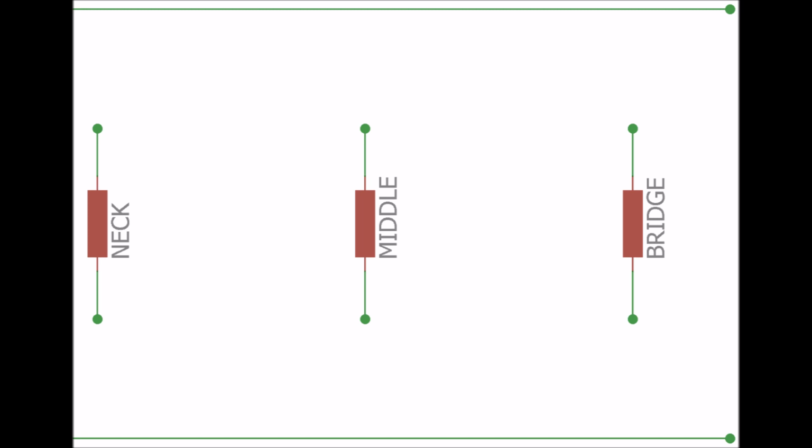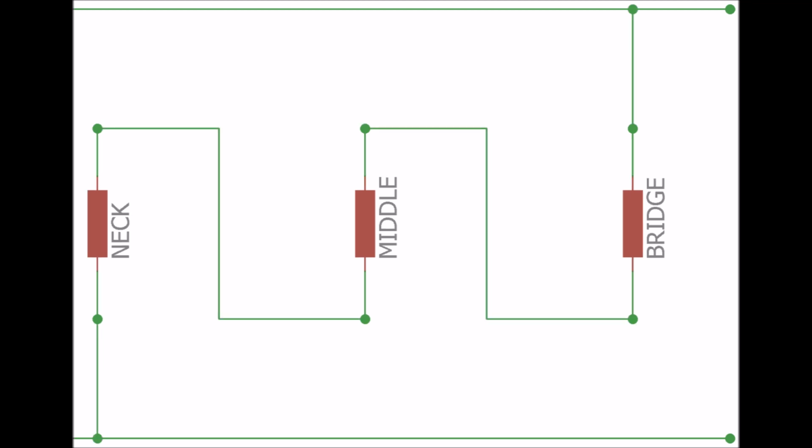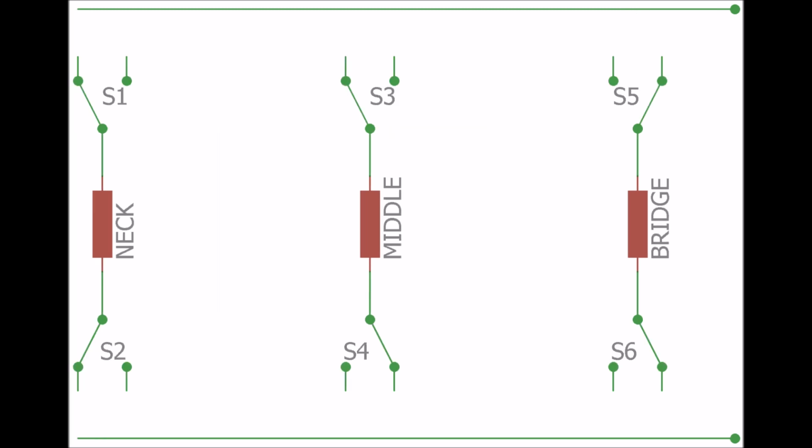Moving on to our final objective of switching 3 single coil pickups in a standard Stratocaster guitar will require adding another position to the switches. With 3 pickups, the switching operations will have to be distributed to both ends of the pickups, considering that in an all-in series combination, one of the pickups will connect or float between the other 2 pickups, and none of its leads will connect to any of the signal or output buses. Thus, 6 SPDT switches will be used, one switch for each pickup lead, but treated as operating in pairs for each pickup.